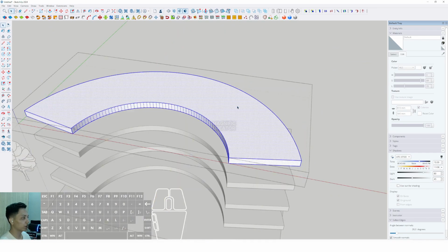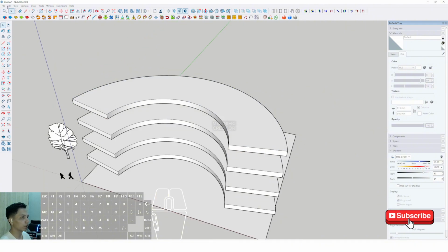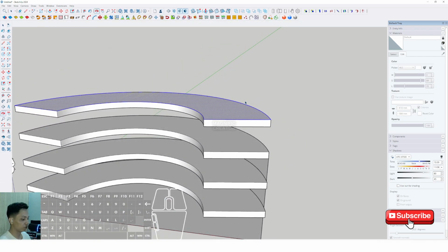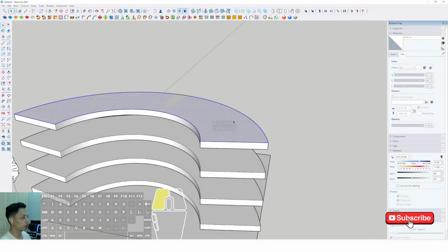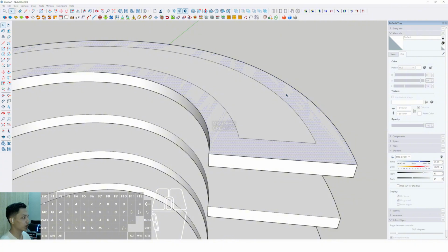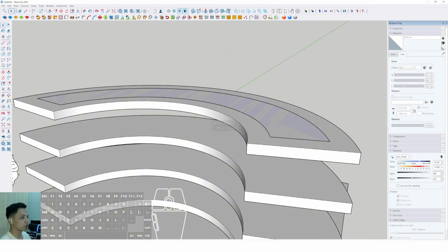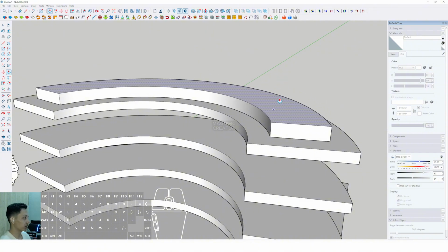Okay, then we can triple click this plane and select edit, copy, exit from the group and edit, paste in place, and we can offset this. We can move this plane first to the above and duplicate, press Ctrl on our keyboard and triple click again for this surface and offset it inside around 2 meters, enter. We can click the extra plane and erase, and then double click the extra polyline over there and erase. Then we can click the surface and pull it up around 1.5 meters approximately.